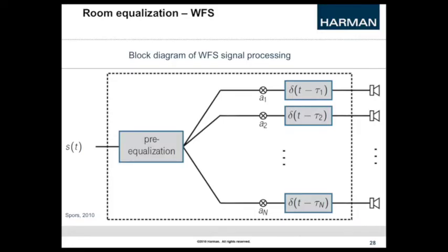It looks quite complicated, but if you dig into it, it's actually not. Now, in the signal flow, you can use this 3dB EQ filter for the input signal, then you split it up, and for each speaker you have one amplitude and one time delay. And that's about it. This is the whole story behind wavefield synthesis. This is also the unknown block, marked with the question mark, that does the room compensation.